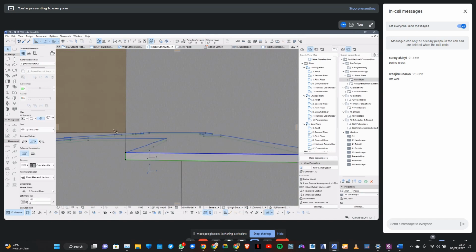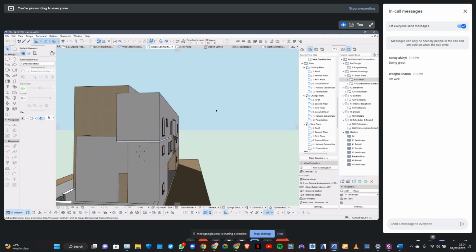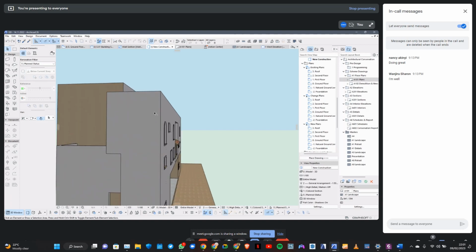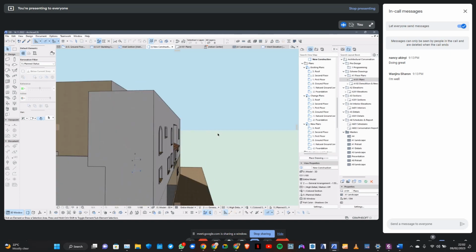So the basic rule of intersecting, making sure that stuff intersects in 3D. Number one, make sure they all lie on the same plane. So I would really need to model intricately, making sure the intersections are okay, the beams, columns, slabs are all aligned, and then make sure that on the plane that you want them to be seen as one, that is the same texture.